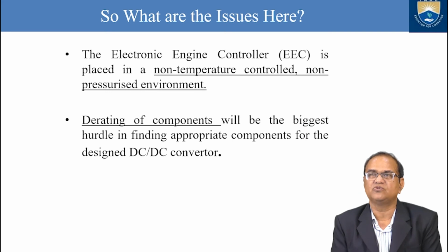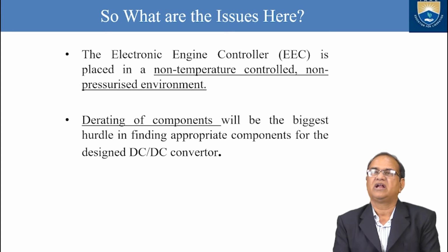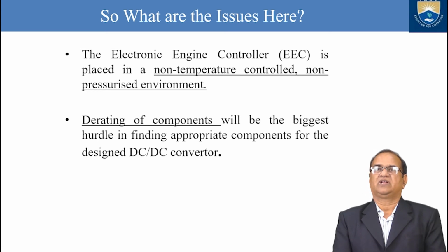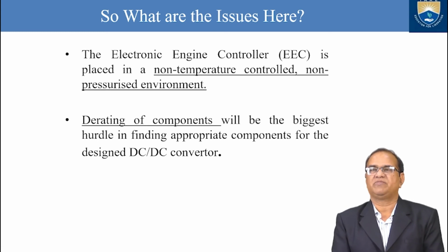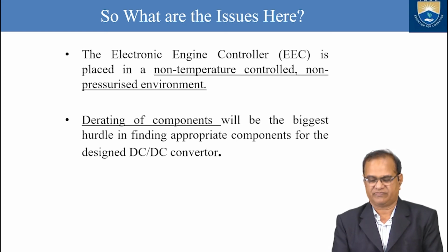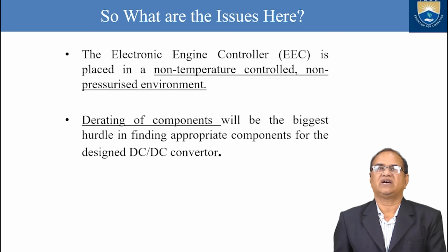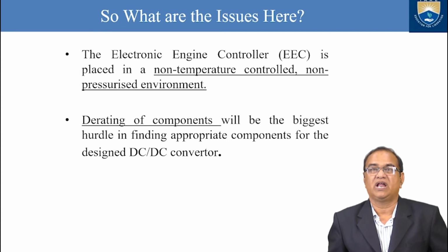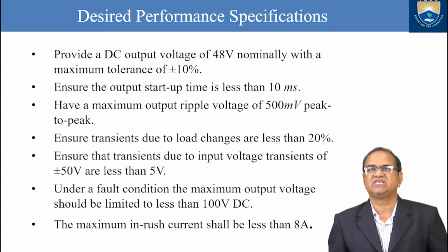So what are the issues here? The electronic engine controller is placed in a non-temperature controlled, non-pressurized environment. Derating of components will be the biggest hurdle in finding appropriate components for the design of the DC-DC converter.